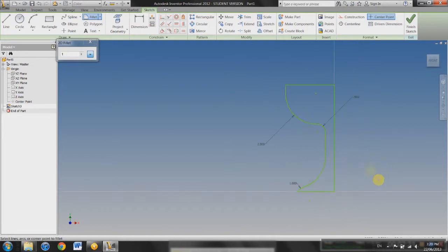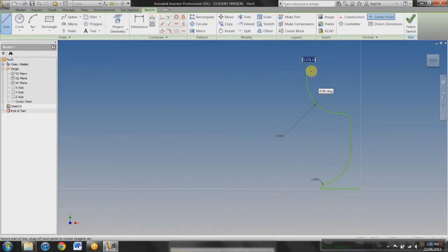Alright, so now we have the basic profile of a wine glass. So just hit the X up here. Alright, just create a new drawing on the inside about the thickness of a wine glass there. Just like that. You can go in here about halfway. And then right to the center. Then hit F again for fillet. Maybe 3.